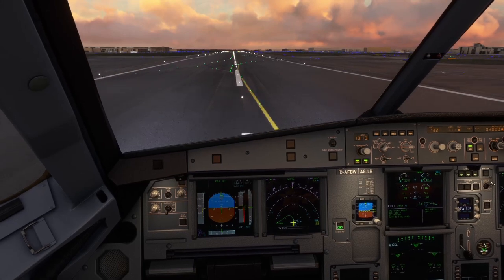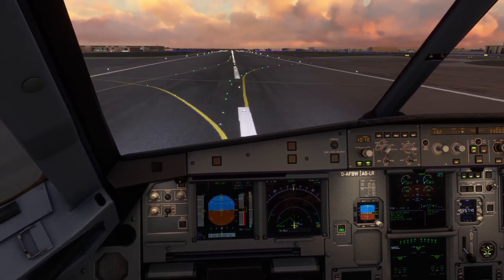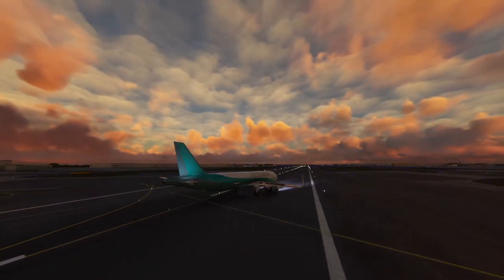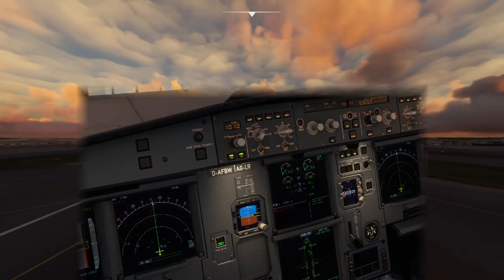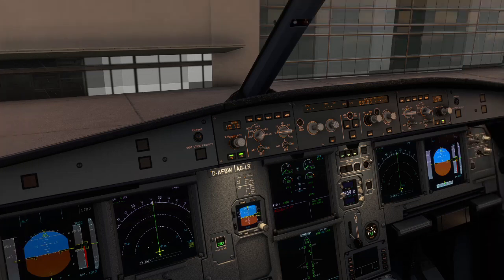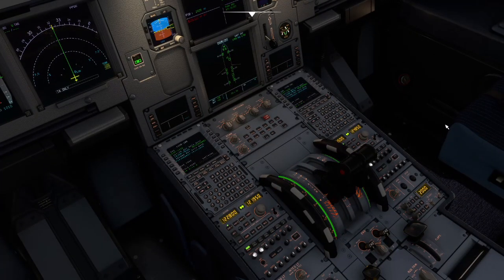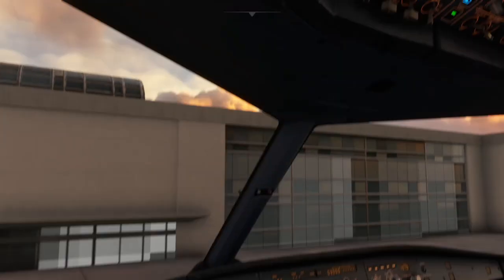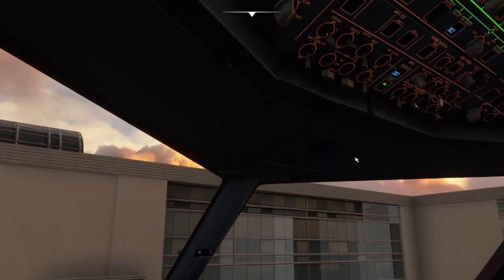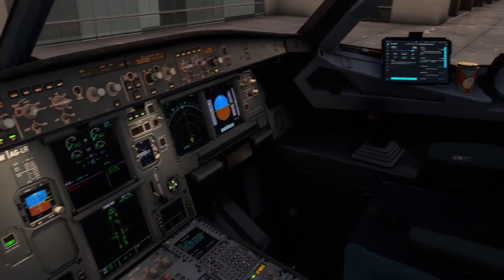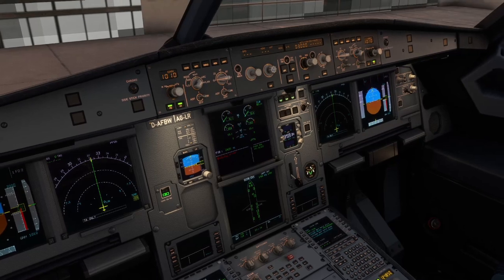This is why I have the APU already started, to be honest. Don't have fancy rotors or anything. That's pretty much us done. Once marked on the gate, check your gate view is up. Both the fuel controls to cut off, sorry, to off. And then you can go seatbelts off and any other kind of realism-y bits you want to do. Happy days, beacons off, strobes off. You can open up your doors, all that kind of stuff. Air bridges come out, but we are not going to get into that stuff.